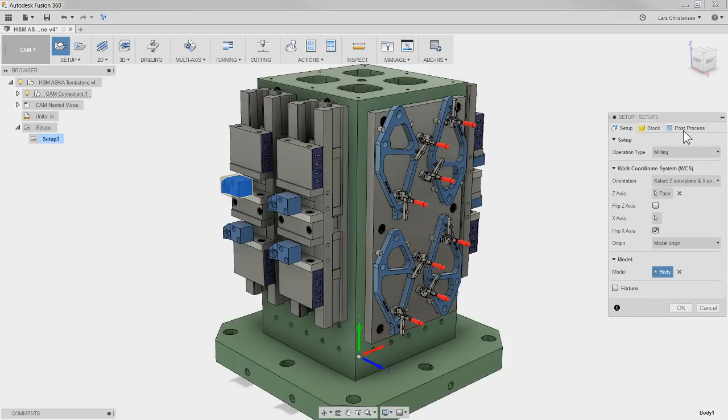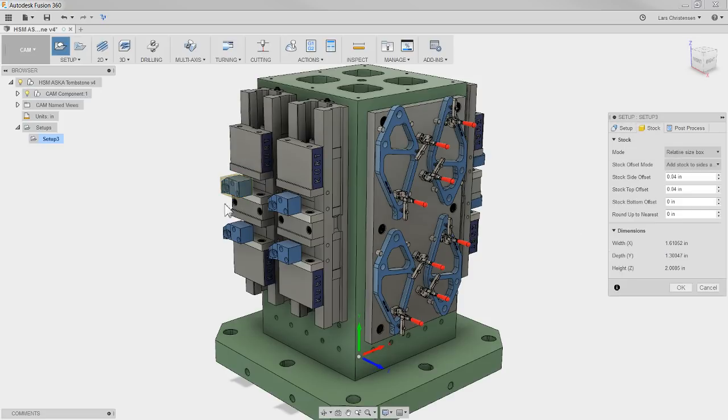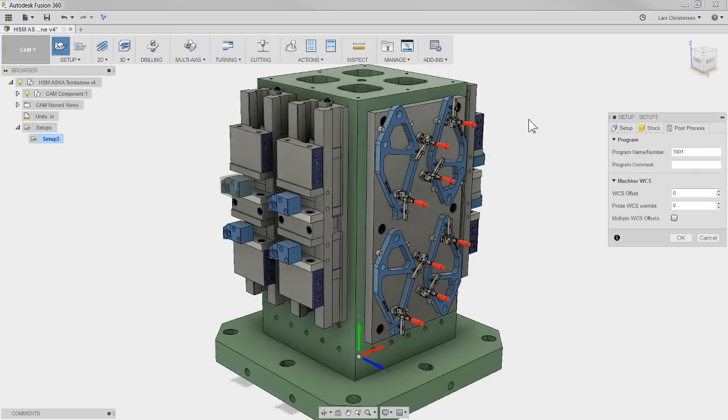Now don't forget, with this set, the origin down there, the stock is still that piece because we selected that, and the post-processor over here works the same way as it always does, that 0 and 1 would be G54. But we are not going to have multiple work offsets if we're doing it this way.